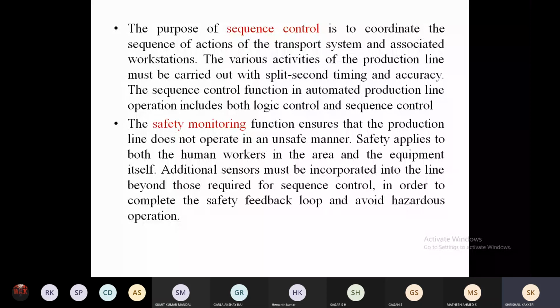For example, an assembly operation happens within a specified work volume or work area. Within this, the operations are carried out automatically by devices, robot arms, or workstations, and if suddenly a human or some unwanted object enters the secondary level, the operation is stopped. That is the secondary monitoring system.